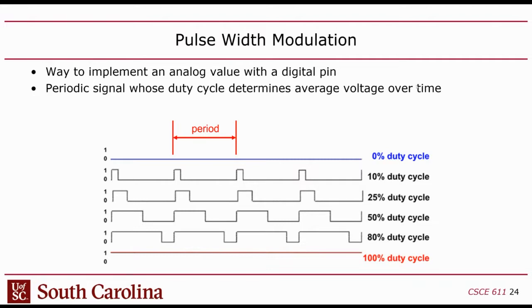The only restriction is that the analog value is going to be between 0 and the VDD, the power supply voltage for the digital signal. So, if a 1 is 5 volts, then you can represent a signal from 0 to 5 volts. Most digital chips are much lower voltage than that now, but some of the lower power ones, like the ATmega, still use 3.3 or 5 volts.